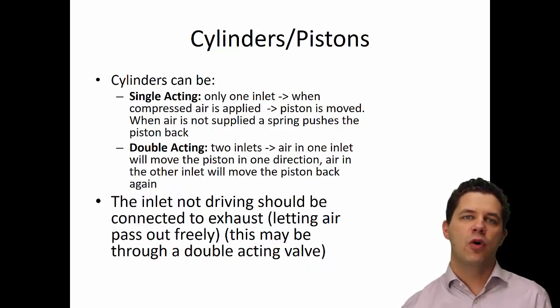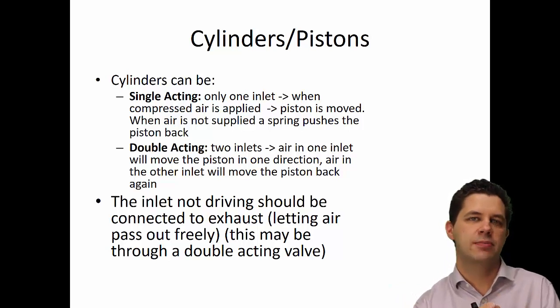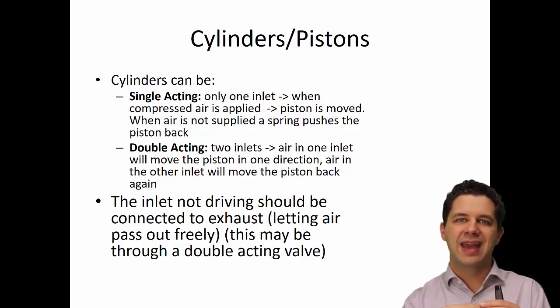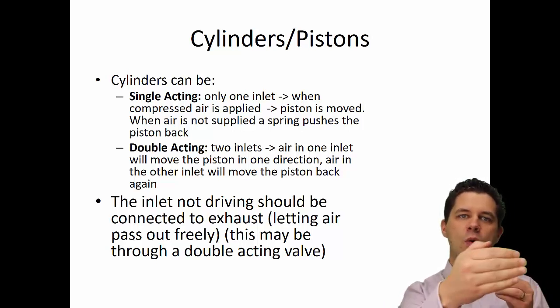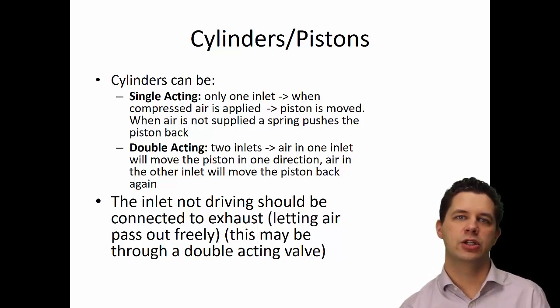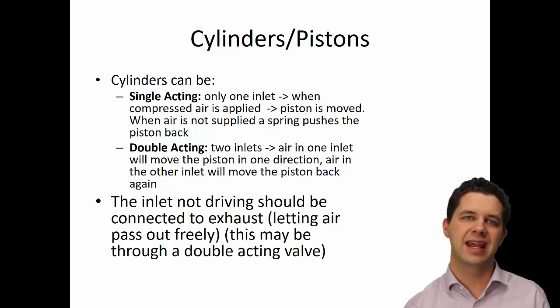Now they can be in a few different forms. They can be single acting, so in this case we only have one inlet. When we apply compressed air or something like that, the piston is moved, and when we don't supply it, a spring will push the piston back into position, so single acting. We can have double acting. This is where we have two inlets. We can apply gas or liquid in one spot and move it one way, and then we have another inlet where we can apply it and move it back in the reverse direction as well. It really depends on what sort of environment we're working in, whether we can have a spring action to take it back again.